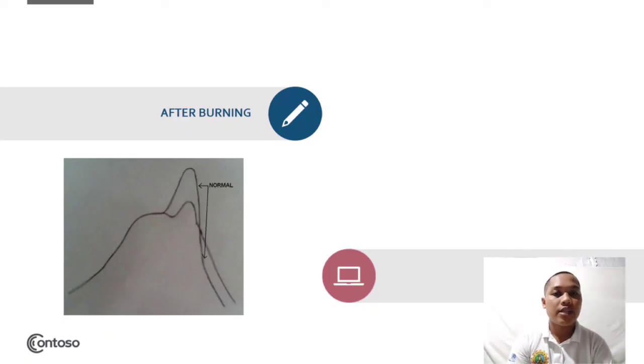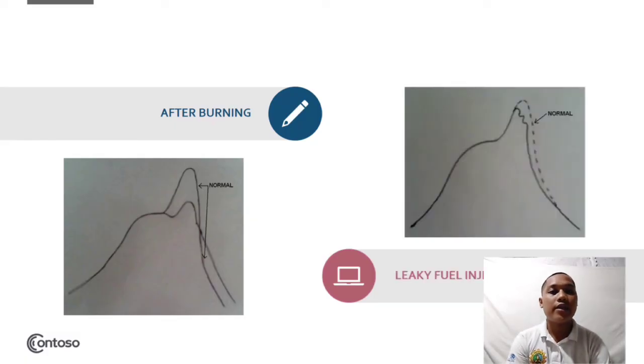Elevated temperatures inside the cylinder cause breaking up of lubrication and increased wear of liners, piston rings, burning of piston crown, etc. Ang mga causes: slow fuel combustion, quality of fuel is less, low temperature of fuel means high viscosity, and leaky fuel injector. So, ang indications and effects.